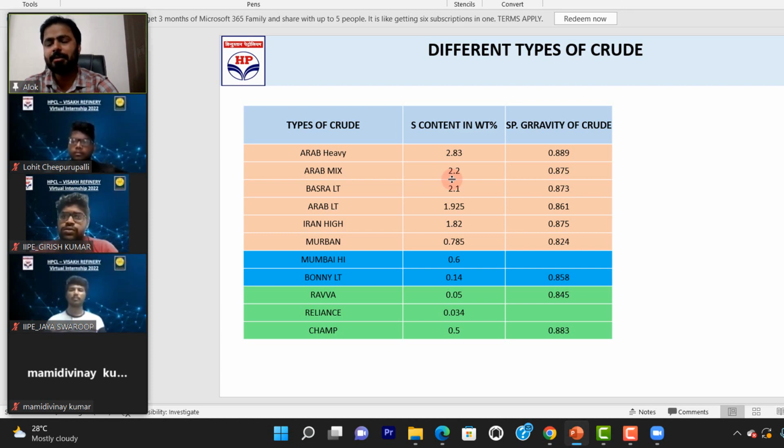So we maintain the regen temperature between 700 to 730 degrees Celsius. Basically we burn off the carbon on the catalyst in the regeneration, we make the catalyst a fresh catalyst, and that fresh catalyst again goes back to the reactor. So this cycle goes on. This is how we establish it. And in the reactor, the temperature we are maintaining is between 500 to 530 degrees Celsius. So we give a set value to the reactor, we want 510 degrees Celsius.